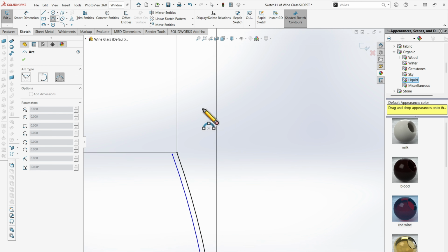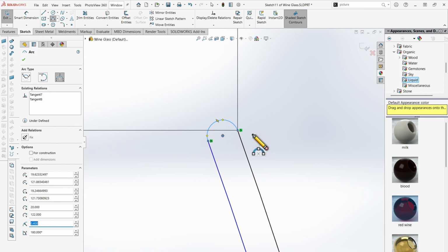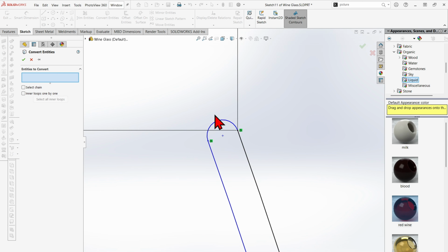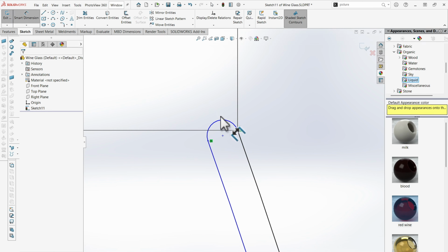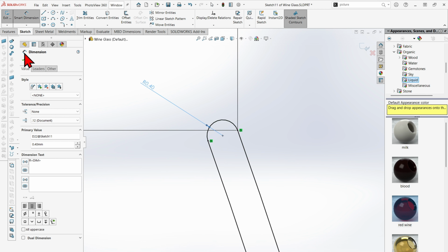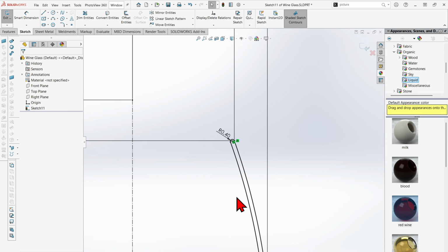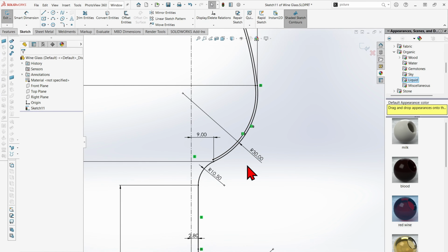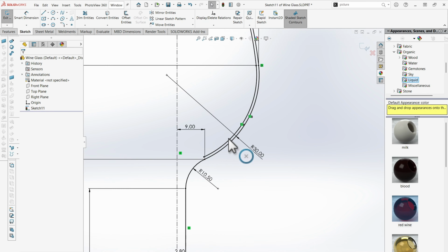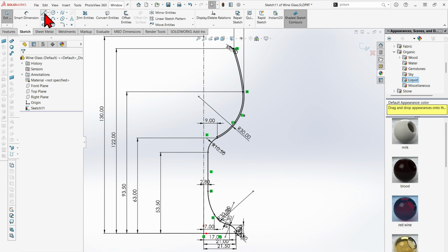Come here, select your 3-point arc, and then select those 2 points, drag that, make sure it's nicely down, dimension that to 0.4 radius, basically equal to the thickness. There, you see, we still don't have any shaded area between the sketches, so we need to make sure our